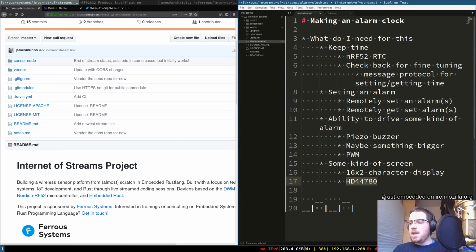And we have a good number of pins here, but the nRF52832 only has 32 pins to start with, and I know some of them are pinned out to the radio and the accelerometer that's on there, so we don't have a ton of extra pins to work with. So we'll probably end up using one of those I2C port expanders here as well.